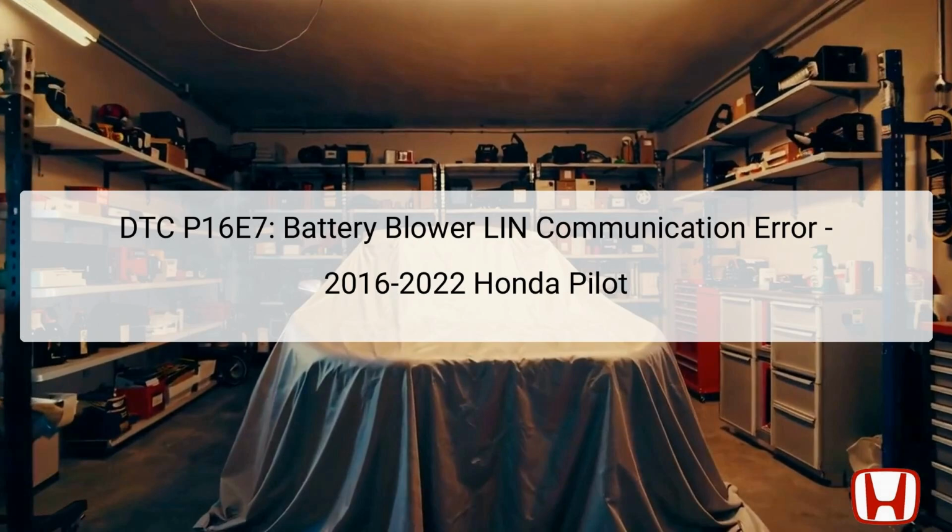The Diagnostic Trouble Code DTC P16E7 refers to a communication error involving the battery blower linear interchangeable network, LIN. This code occurs when the vehicle's powertrain control module, PCM, detects an issue with the signaling from the battery blower motor. Communication errors can significantly impact the overall functionality of the cooling system, potentially leading to overheating or inadequate cabin